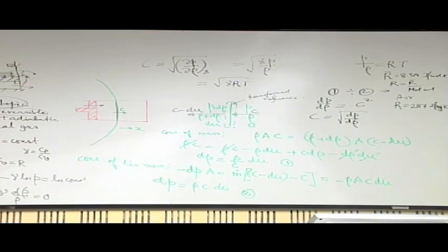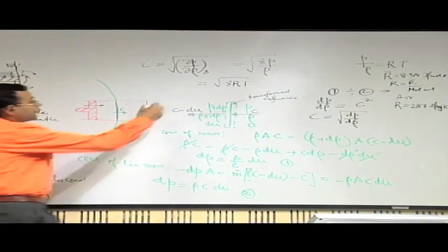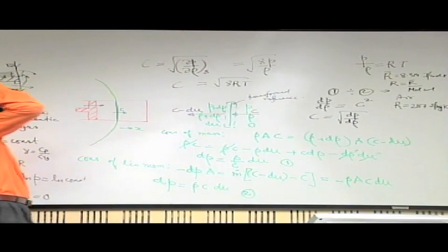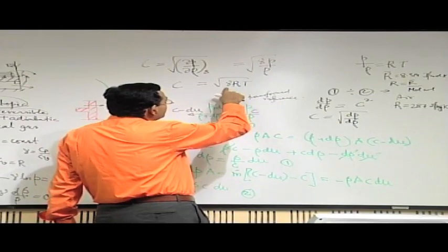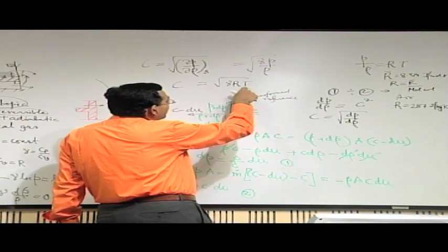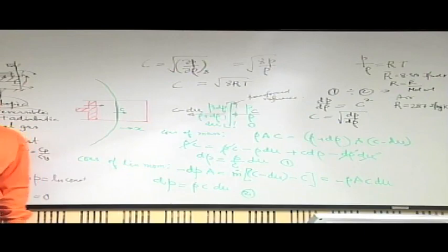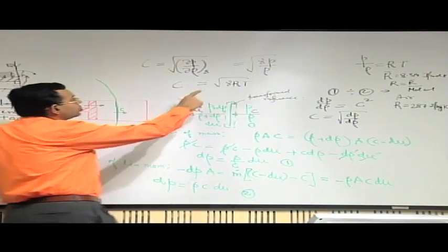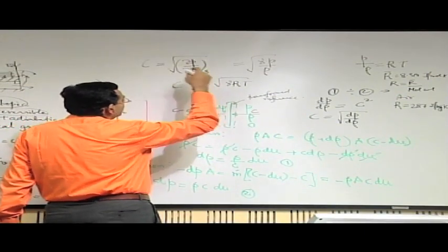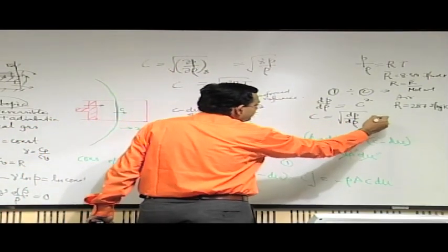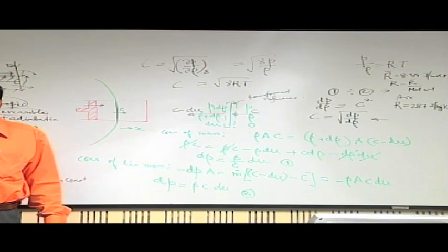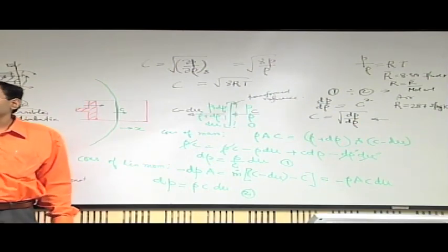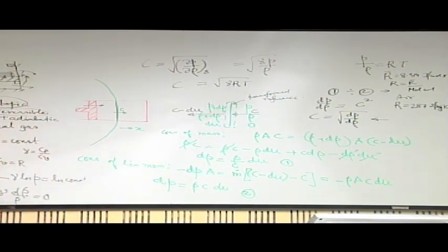So we can see what the factors are on which this sonic speed depends. It of course depends on the gas constant, on the Cp by Cv and the absolute temperature, but we have to keep in mind that this is not the most general expression. The most general expression will be this one, because depending on the nature of the process dP by d rho will have different expressions. This is for an isentropic process.